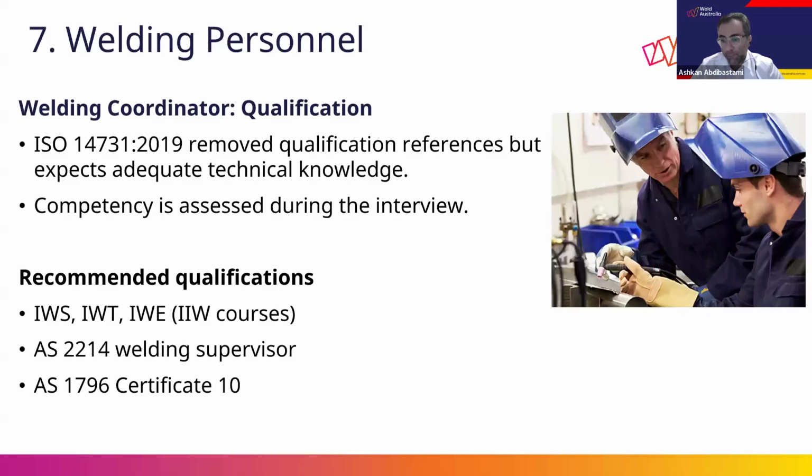And if the welding supervision has lots of activity, the welding coordinator should be full-time and spend enough time to manage the activities. For example, if the welding coordinator is external and let's say participates on site 2 days per week, maybe it's not enough to do the welding supervision activities as well. And this is the most important thing.